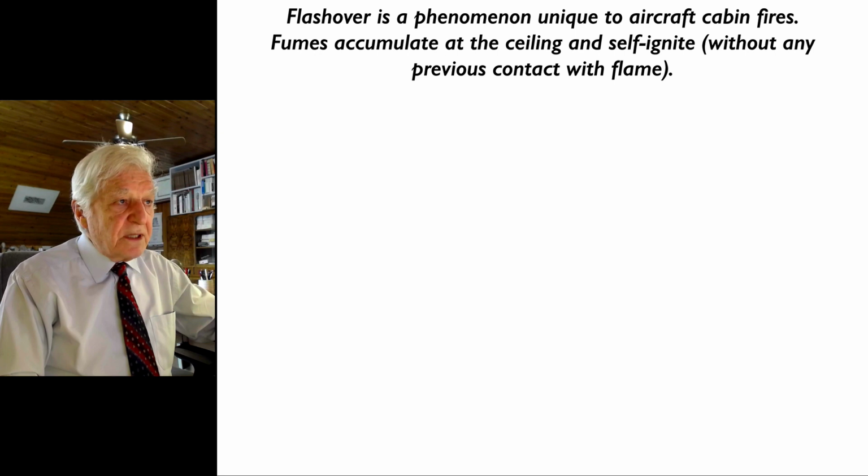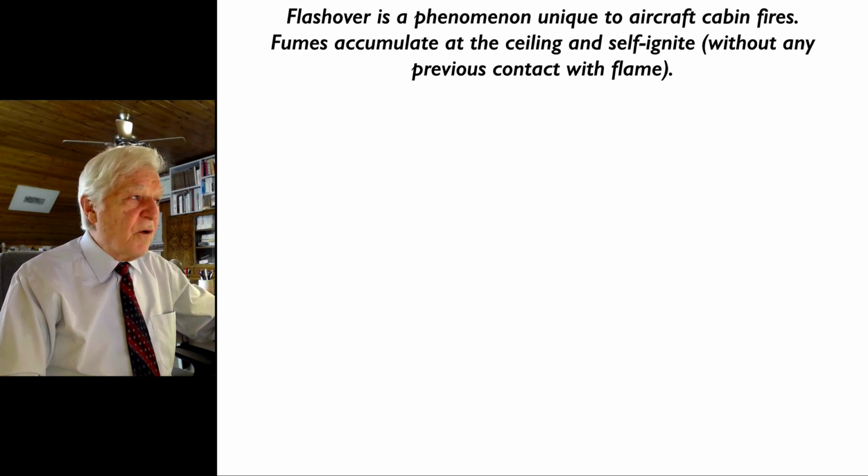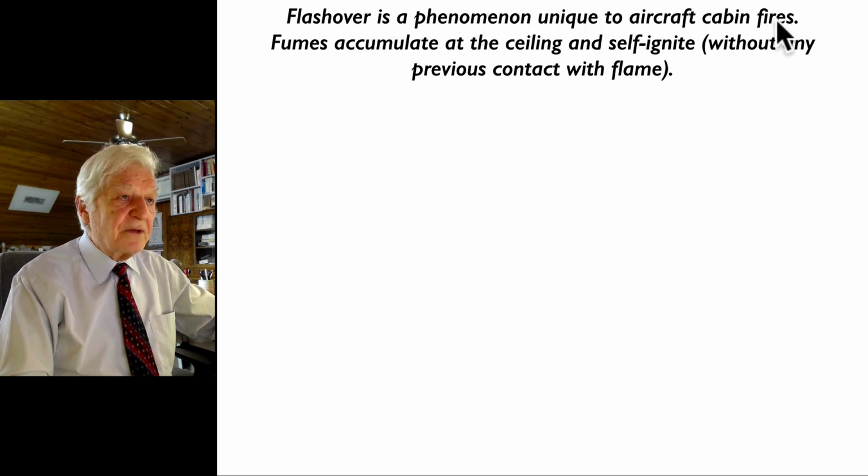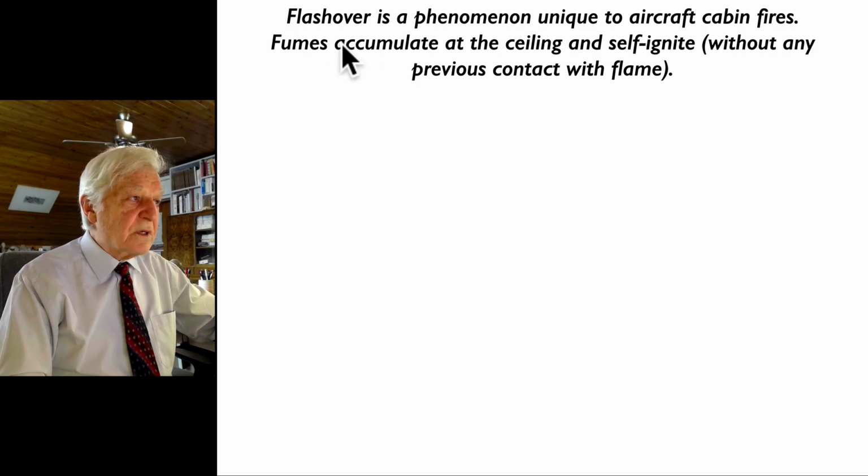What has been investigated is what is called the flashover. Flashover is a phenomenon unique to aircraft cabin fires. Fumes accumulate at the ceiling and self-ignite without any previous contact with flame.